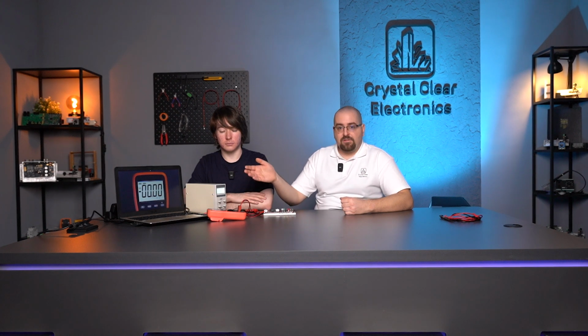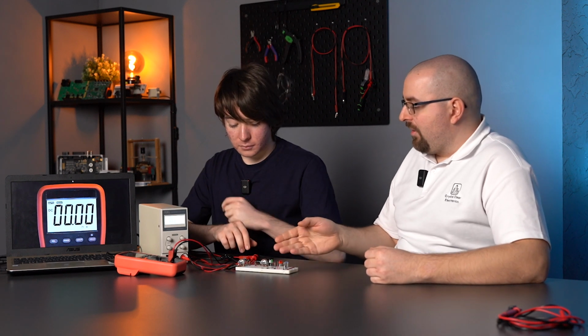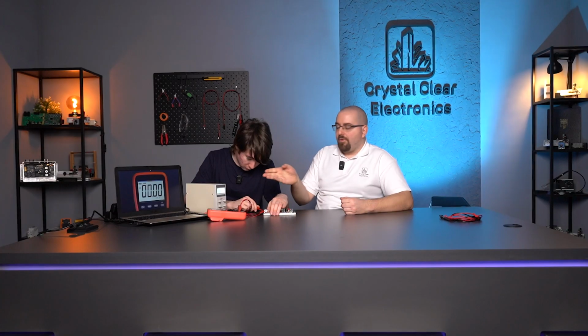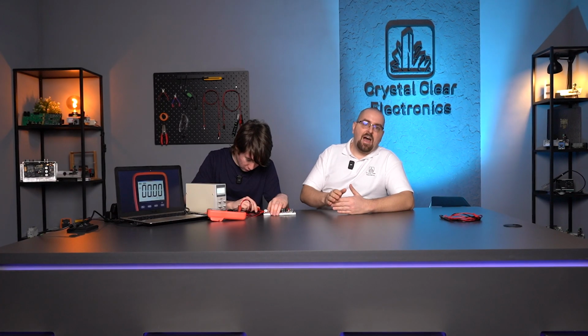But let's examine this in practice. Here we have a lab supply. It will be the input, the V1 voltage source set to 12 volts. Now we will ask Marci to be so kind as to connect our multimeter in series with this power supply in the current measurement mode. So we are measuring the current consumption of this circuit.